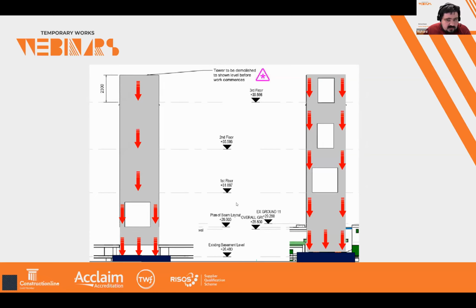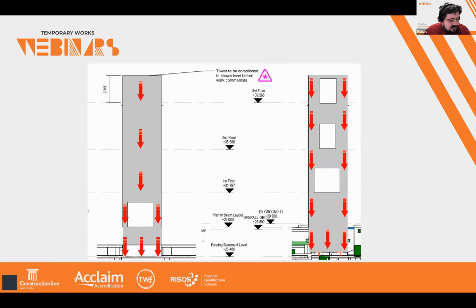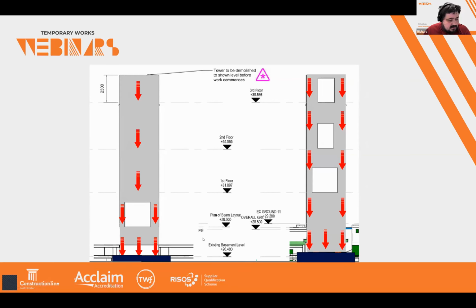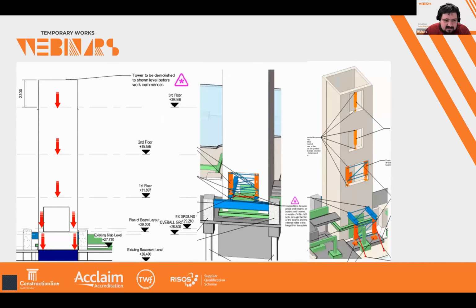And what we wanted to do was pin the entire thing so that we could extend the lift shaft down. So at the bottom, you can see, compared to the previous one, there's going to be a big gap at the very bottom of this load path. As Josh said earlier, the load tends to want to go back into the ground, and we've just disconnected the entire thing. So we needed a design to redivert these load paths through all these propping arrangements.